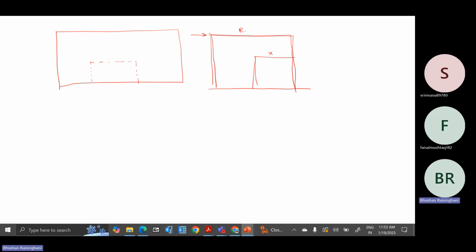However, it will be given a rigid diaphragm at this particular level in the elevation side view that I am showing to you, right? So that way, a small portion of the slab inside the building at this particular level will all behave in a rigid manner only. At this level, we don't require it to be considered.